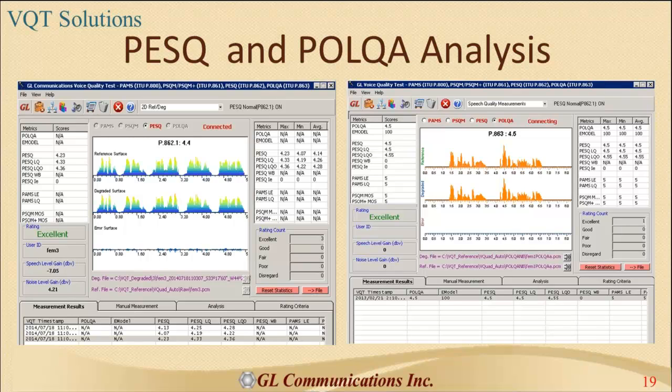Yes, Shelley, that's sort of a tricky question. It's a good question, but it's a tricky question. POLQA can be used for all networks, but PESQ has a lot better analysis metrics that come from the algorithm. For instance, with PESQ we get the signal level and the noise level and clipping and jitter and things like that, whereas with POLQA you don't get all those different metrics.